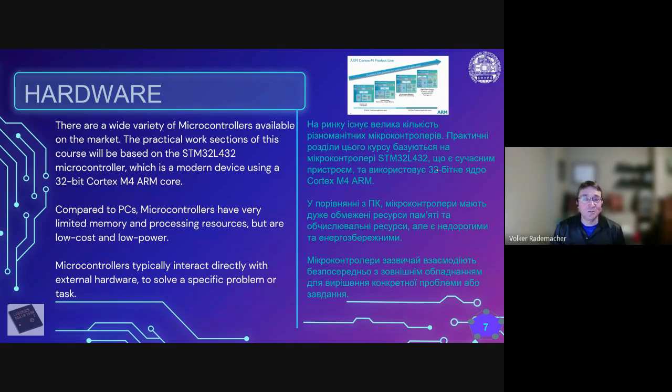It is meant to indicate that, for example, a pointer update of a 16-bit pointer has to be done in 2 write cycles. If an interrupt happens within these 2 write cycles, there can be a problem if the same pointer is being used in the interrupt. So using a 32-bit microcontroller avoids all of these problems right from the start.